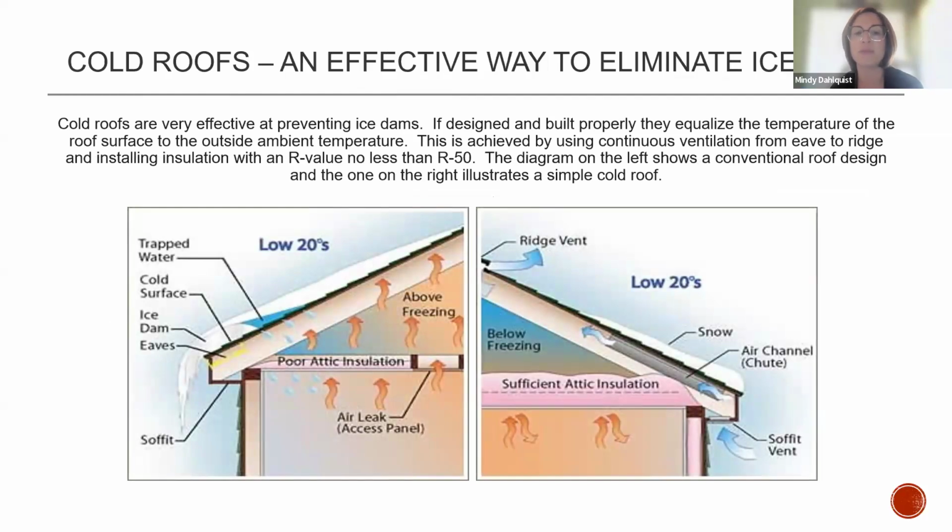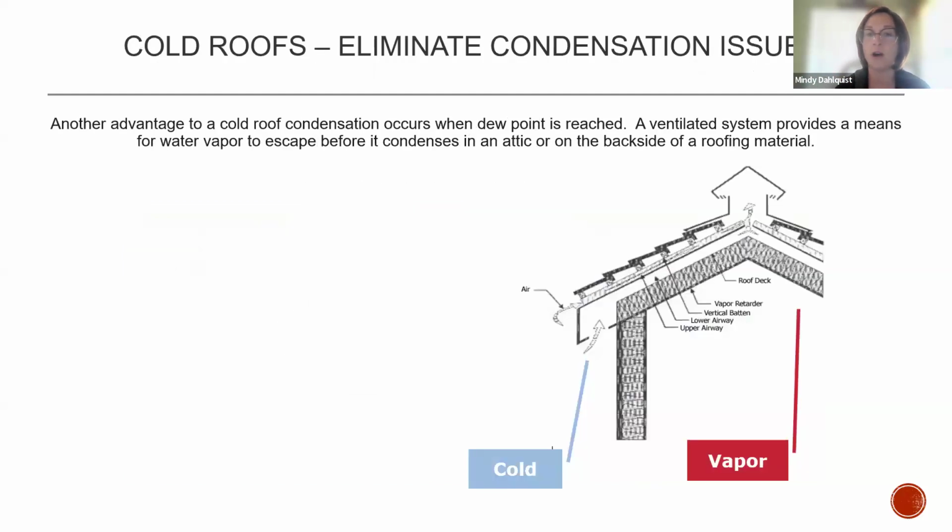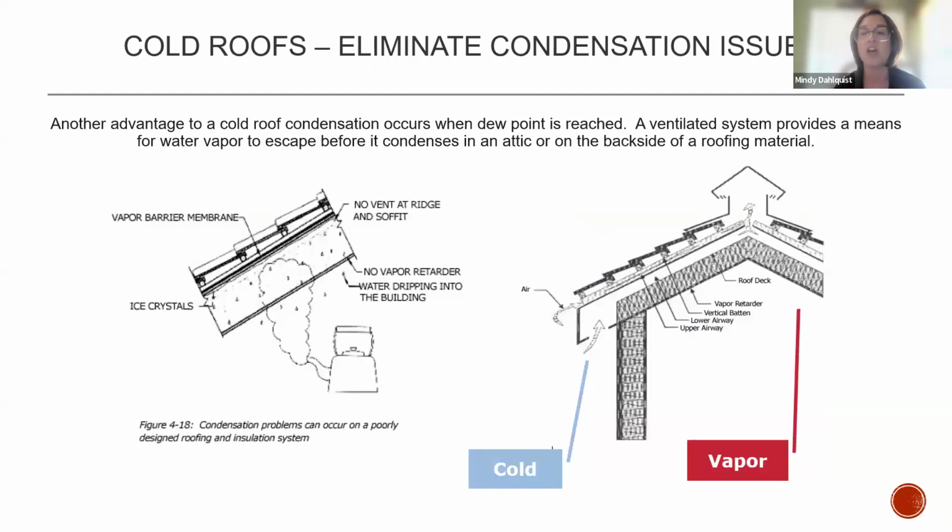Your traditional roof system is on the left, where you have those differing temperatures, that water's being created from the snow and ice. That's all melting, becoming water. It gets down towards that eave. It's refreezing, solidifying more into ice. That water's coming back behind that ice, comes out over top as icicles, or it sits behind in that warmer space and just sits there as water on your roof. And that is where you usually see water intrusions start to happen in your buildings, is when you have those ice dams and the water's backing up behind it. So if you're seeing icicles, there's already ice damming that's occurring.